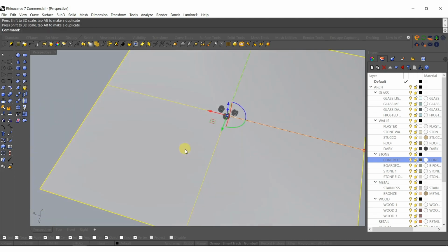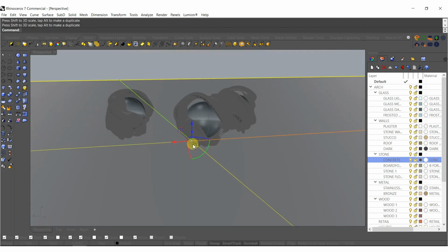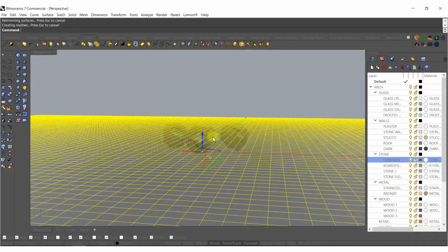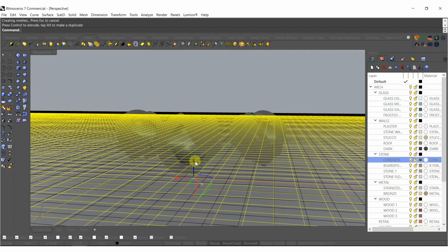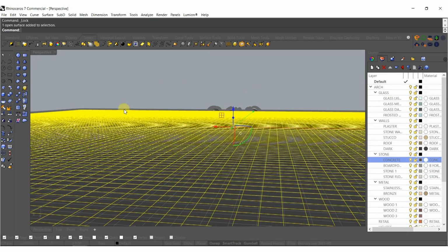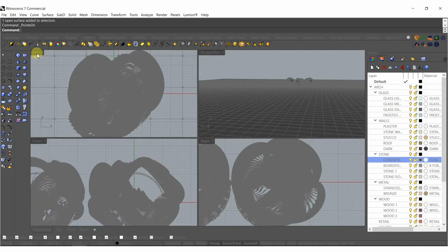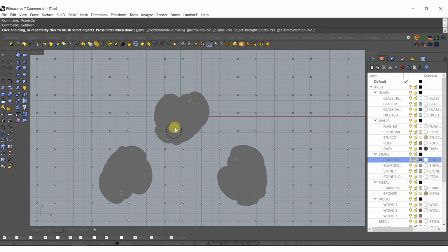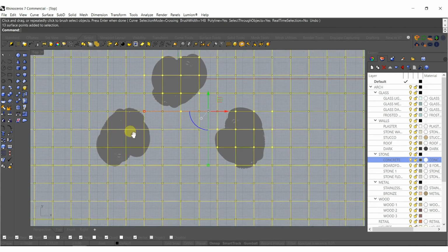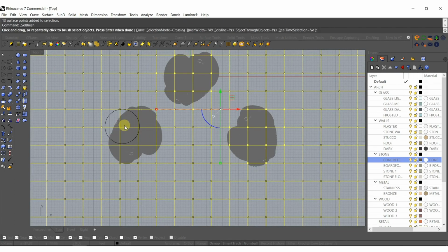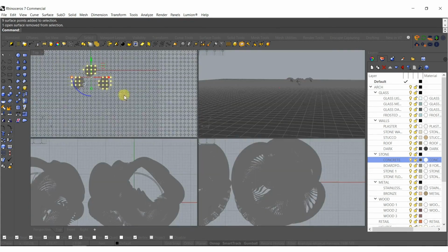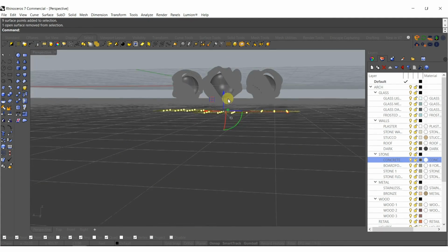Let's do our sand. What I'm going to do is type in invert, lock everything down. We're going to turn on our points there. And what we can just do is pick up right underneath here each one of those points. I'm going to end up moving this one over, so I'm just going to pick up this island there. Awesome. All we need to do is just pick those up so it's quite a ways above the water. So what we'll do next is smooth it. Hit OK.